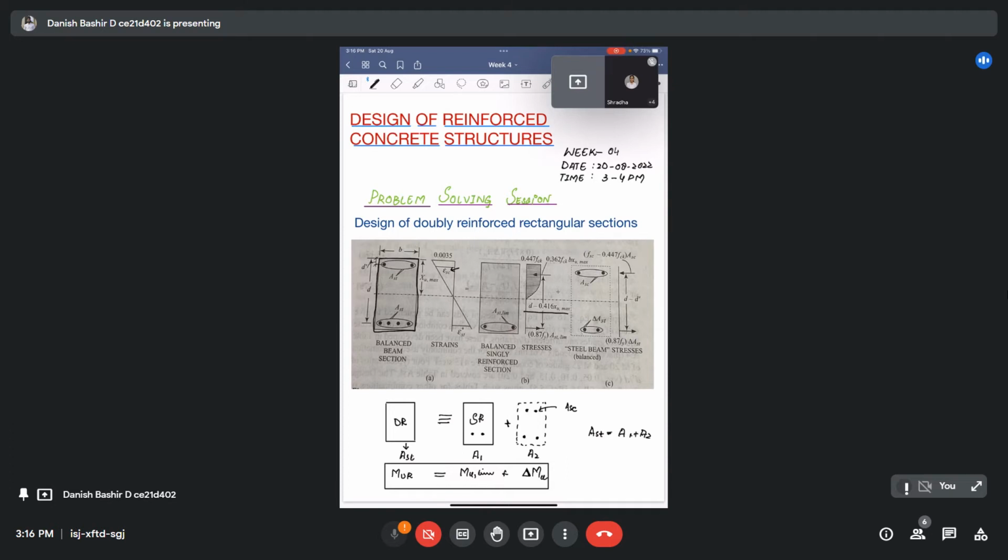And for this steel-only section, that's why it's shown in dotted line, because it's actually not a concrete section and reinforced concrete. It only has compression steel, which is creating one compression force of (fsc minus 0.447 fck) Asc, and down at the bottom is delta Ast, which is the Ast minus Ast limiting that I provided here.